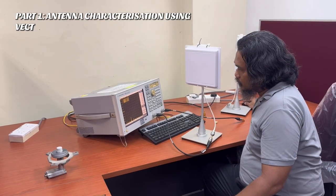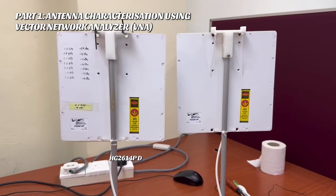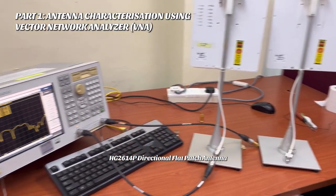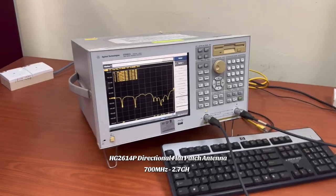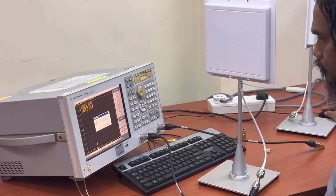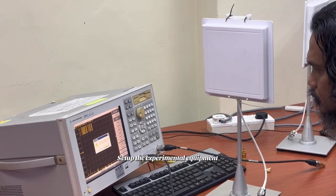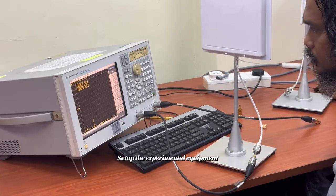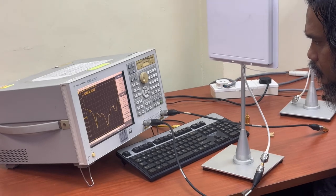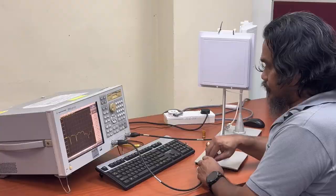Part 1, Antenna Characterization using VNA. For this experiment, we are using the HG2614P directional flat patch antenna that operates in the frequency range of 700 MHz to 2.7 GHz. First, we set up the experimental equipment by connecting the antenna to the Vector Network Analyzer, and then the VNA is configured to sweep frequency from 700 MHz to 2.7 GHz, which covers the antenna's operating range.